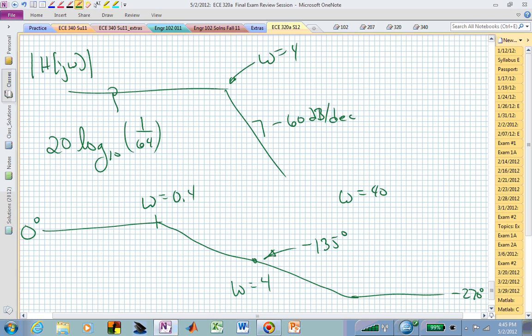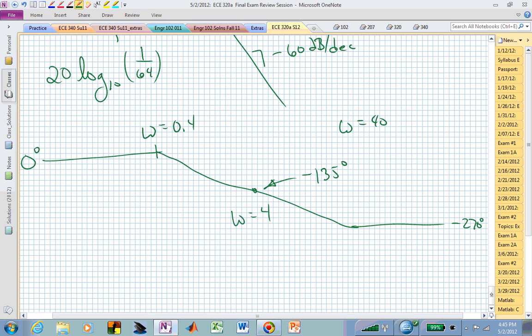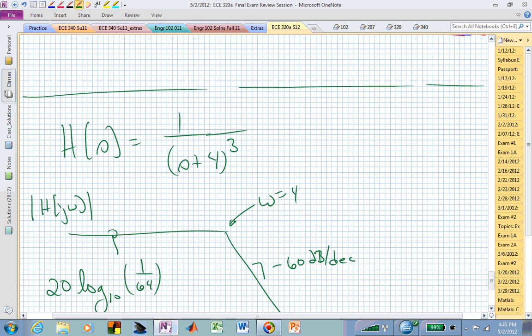Does that help? I could ask you all sorts of questions, especially in multiple choice. I could ask you what's happening at low frequencies, what's happening at high frequencies. I could say, what's the slope of this at low frequencies? Magnitude. What's the slope of the magnitude? Low? Well, you tell me what's low. What's a low frequency? Anything below the cutoff, right? So now what's the slope? 0. It's not sloping, is it, in magnitude? So you have to just think, what does he mean by slope? Well, I mean it's flat. If there's no slope, there's 0 dB per decade slope.